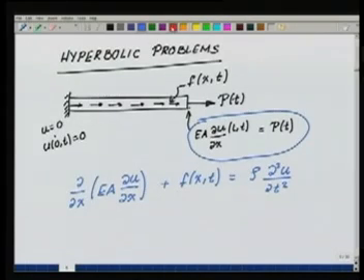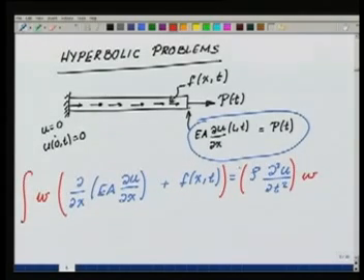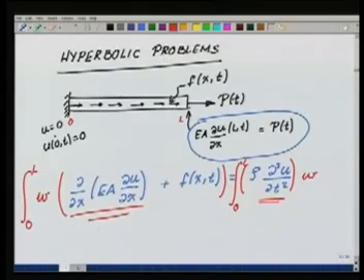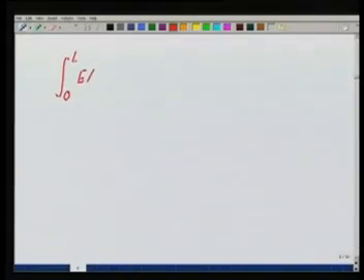Okay. So I will multiply this by a w, multiply this by a w, and integrate from 0 to L. This is my L, this is 0. Then I integrate this part by parts. Remember, we are not going to do anything to this because this does not have a spatial derivative sitting here. So we'll do integration by parts, and this will give me, if I go to the next one, integral 0 to L EA del u del x del w del x,